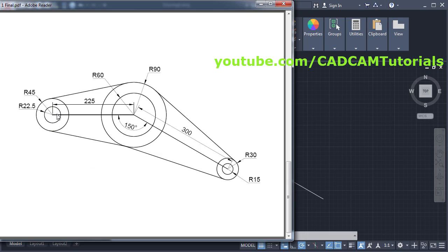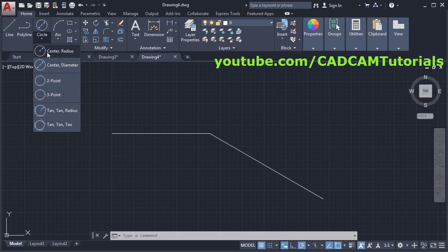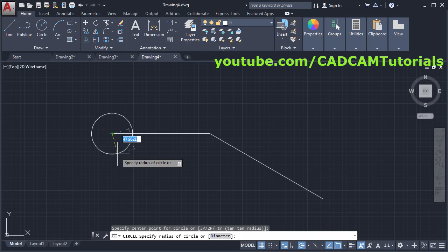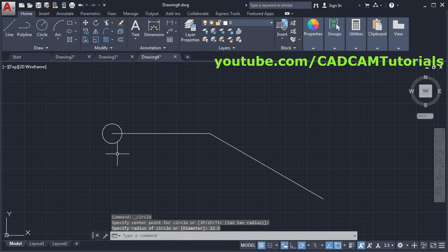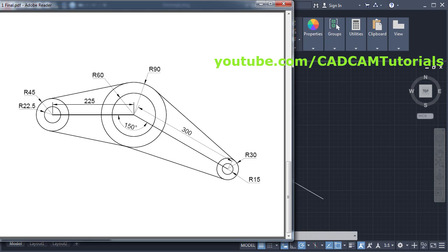Then create these circles 22.5 and 45 radius. Click here and select center radius. Give the center point, click the center point, give the radius of 22.5, enter. You can repeat the previous command by pressing enter. Enter, give the center point, give the radius of 45, enter. Then 90 and 60 radius.